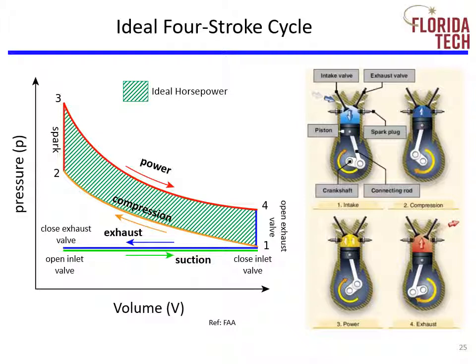Once the piston has reached the base of the cylinder, it's time for the second stroke, compression. During this phase, the intake valve is closed and the piston reverses direction, moving back towards the cylinder head. This compresses the fuel-air mixture since it has nowhere to escape.